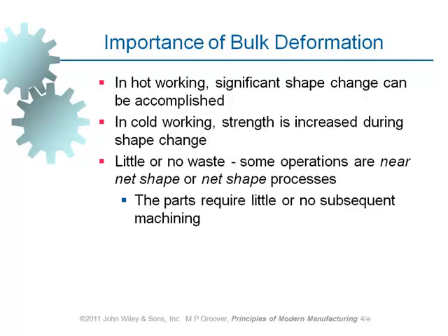If the process is taking place at a temperature below recrystallization temperature, it's called cold working. Even if temperature is above room temperature, say for example for pure iron, if it is being processed at a temperature of say 400, 500 degrees C, which is well above room temperature, this is not considered as hot working. This is still considered as cold working.